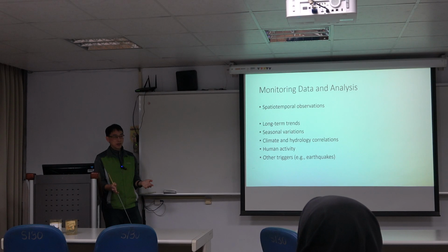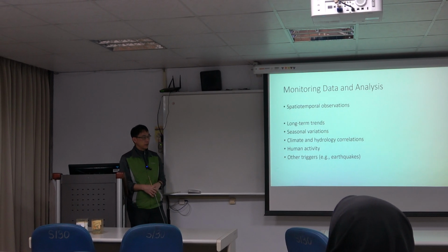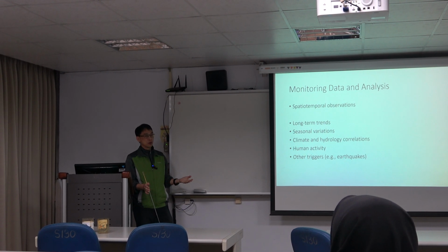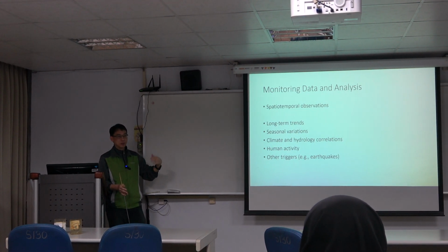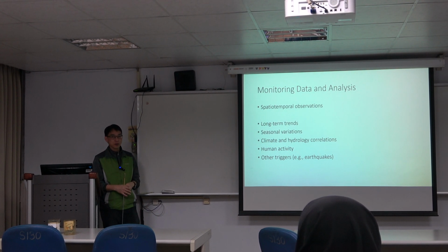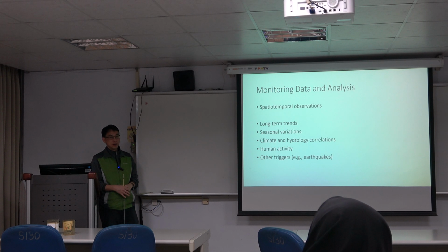It depends on what target you would like to assess. If the quantity you assess is relatively small, then it will be more affected. But if you assess groundwater resources, then several centimeters or 10 centimeters might not be significant enough to affect your result. So the barometric effect could be ignored. But if you assess some other things, you should be careful.